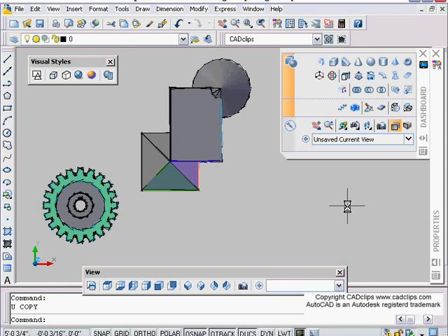Hello and welcome to another CAD clip on AutoCAD 2007 3D, and we're going to talk about the slice command, similar to our section plane command that we did in an earlier lesson. Section plane is different in that it retains the part that's being sectioned off, and then if you erase the section plane, the removed part that is being sectioned away comes back. So slicing really slices it in half into two parts, and you can retain one or the other.